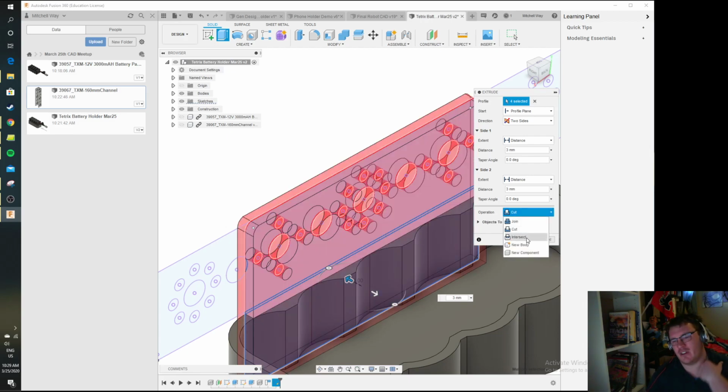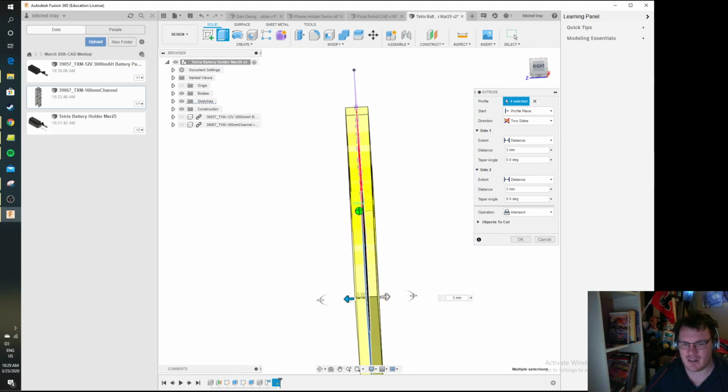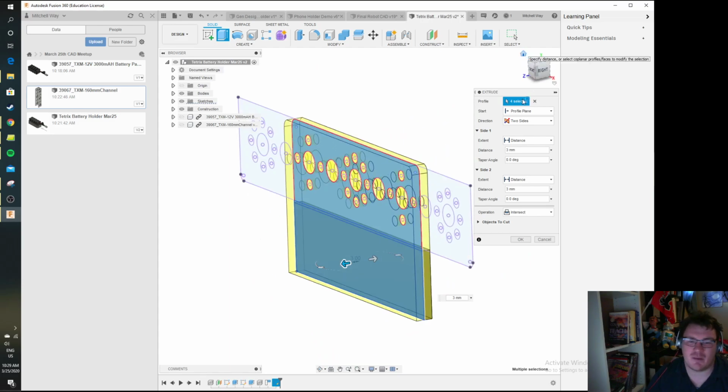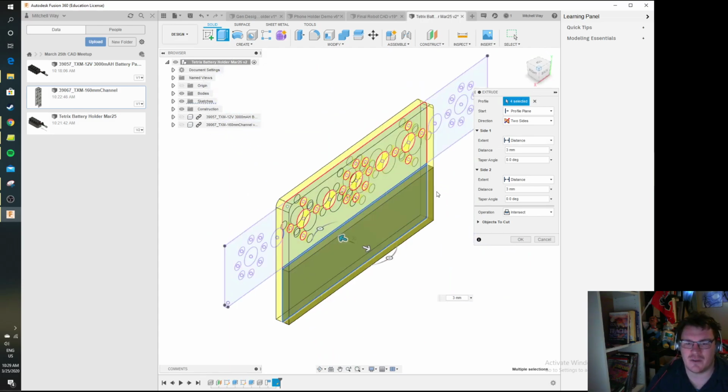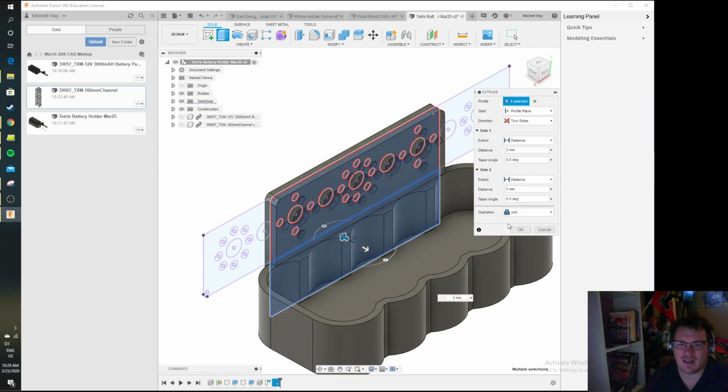You also have another option. If you wanted to draw two shapes and only put material where they're going to intersect, everyone sees this little darkened piece at the bottom here. That's actually sometimes useful in CAD. I've seen it used a few times, but for the most part we stick to join and cut. You're also welcome to make new bodies or components from this. For the sake of where we're at with CAD, not very important. We'll probably use that a little bit later on.